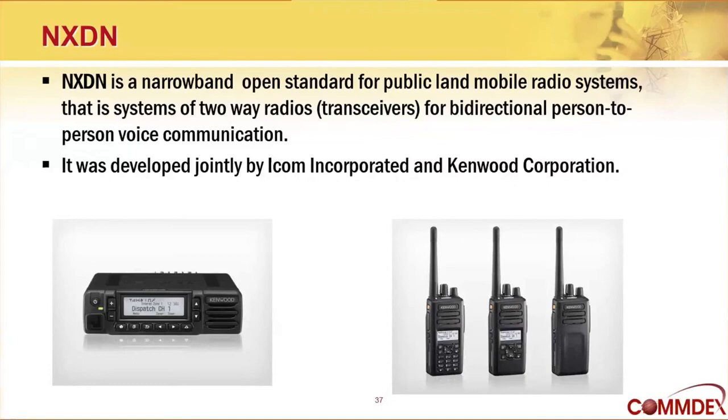And the last technology I'm going to talk about is called NXDN. That's the newest player in the scene. It's narrowband. It's an open standard. It was developed specifically to go narrower than the other technologies. It has the capability to operate in two different modes, either a 12.5 kilohertz bandwidth mode or a 6.25 kilohertz bandwidth mode. NXDN was developed jointly by Icom and Kenwood, both Japanese manufacturers.